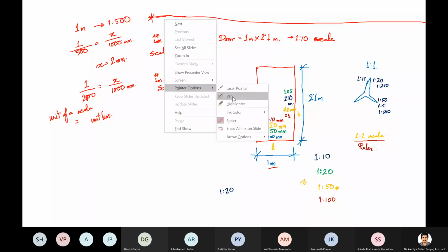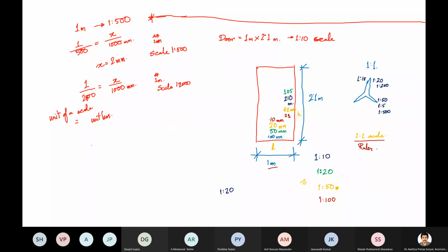Of course, it varies depending on where the wall is. An internal wall is probably around 4.5 inch, converting to around 120 mm. The external wall is probably around 230 mm, or working wise, 250 mm.